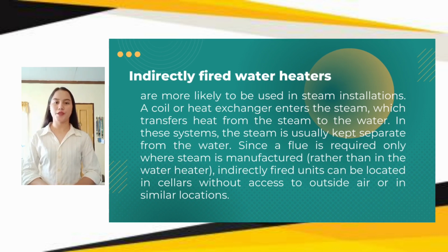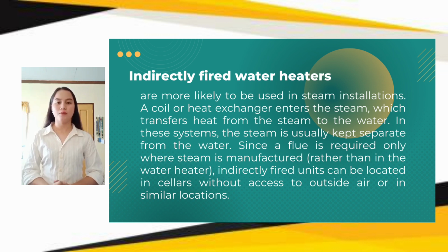Indirectly fired water heaters are more likely to be used in steam installations. A coil or heat exchanger enters the steam, which transfers heat from the steam to the water. In these systems, the steam is usually kept separate from the water. Since a fuel is required only where steam is manufactured rather than in the water heater, indirectly fired units can be located in cellars without access to outside air or in similar locations.